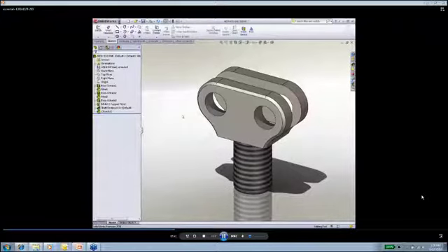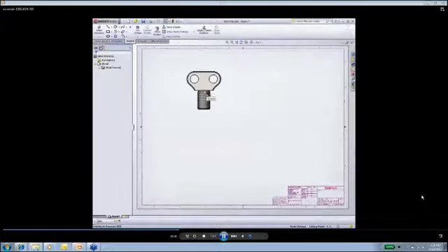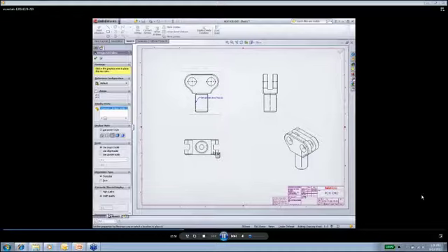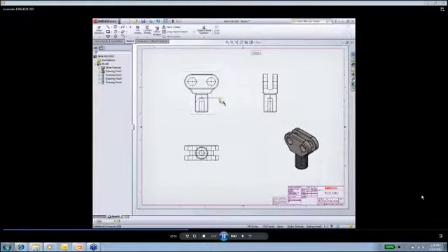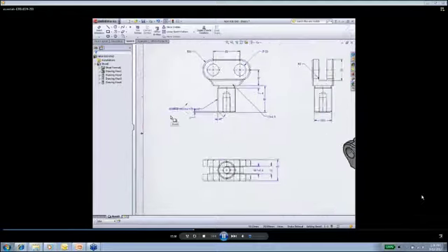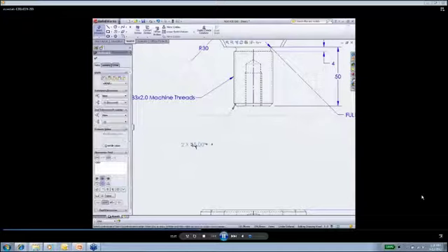So I'm going to go into SolidWorks drawings. I'm going to save my part first, and then I'm going to open up a drawing. I have a series of formats I can pick from. I've selected a C-size format, and I can drag and drop all the views of my part from our design palette, or our view palette, into the drawing. It's very easy to go in and create dimensions, or I could bring in all those dimensions and reuse those dimensions that I created during the part creation.